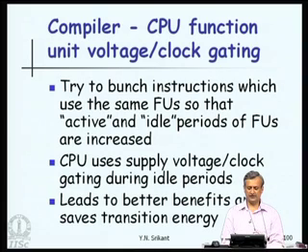So, the CPU uses supply voltage clock gating during these idle periods, that is done by the hardware, whereas the rearrangement of instructions, so that the instructions which use the same function unit are bunched together, is done by the compiler. So, this leads to better benefits and it saves transition energy in the CPU as well.